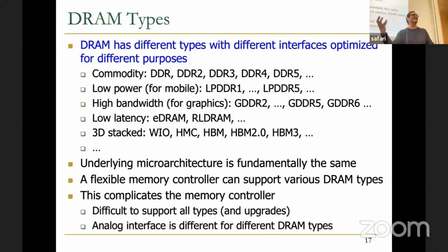But this means that there's still additional latency, right? So you can probably access different kinds of memory chips more flexibly right now with the Compute Express Link type of interface, but that leads to higher latency. There's no way around it, I think. Once you go off chip to another chip, and that other chip does the memory control functions and scheduling, you're going to get more latency.